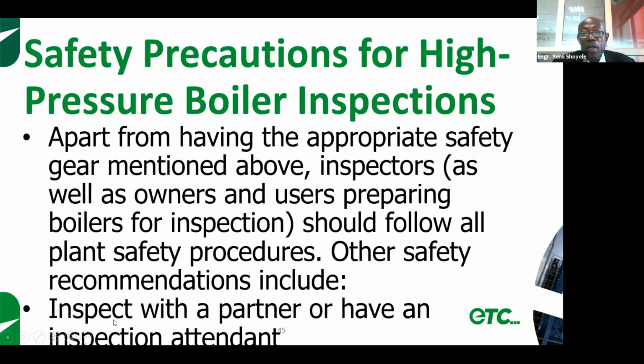Now, please never go inside the boiler unless you are two. Now, in the case of water or fire tube boilers, where you can only accommodate one person, especially on the water side, have an attendant or a partner standing outside the boiler with a hammer, and when he gives one tap, he wants to find out how you are, and you inside the boiler will have to reply with 2 taps so that he knows that you are alive, please.